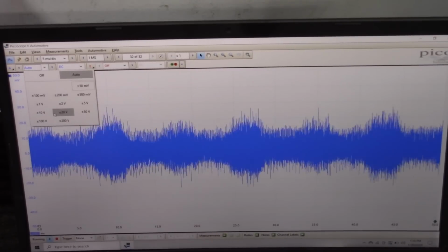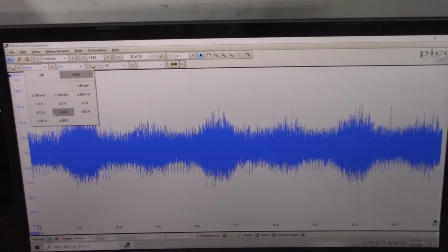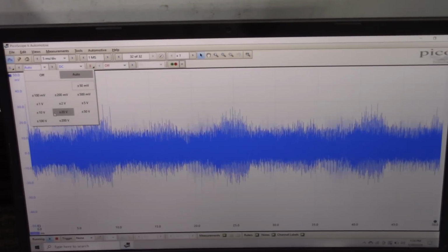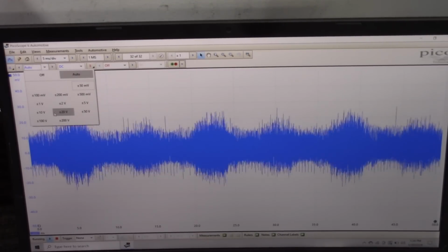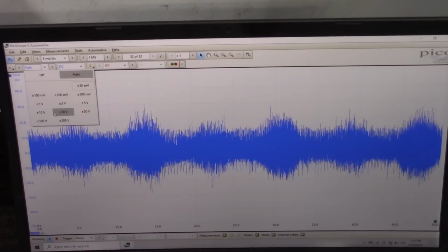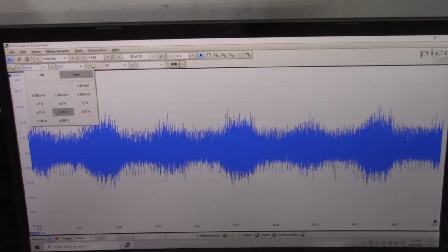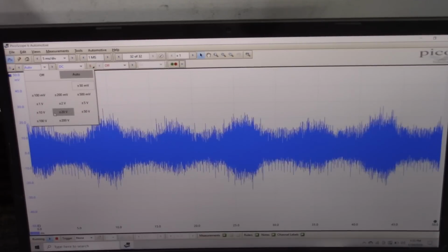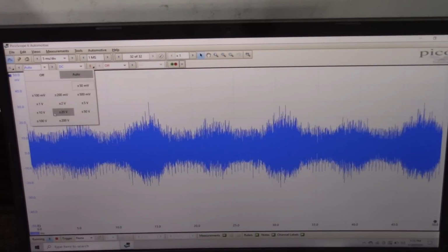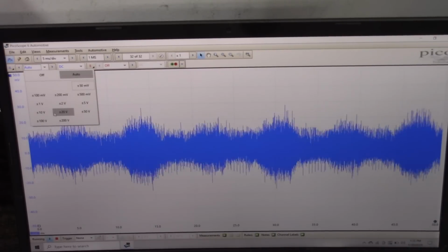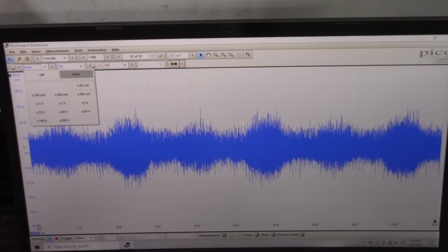Now, we also know, if you watch this channel, we're going to have a little surprise. We expect the voltage is going to be 12 volts, on or off, on or off, 12 volts. That's actually not going to be the case here because, again, this is a solenoid essentially. And we know when the solenoid turns off, it's going to actually generate a voltage from the collapse of a magnetic field in its own. So we're actually not going to see quite what we normally expect with just a simple on-off like I showed on the board. But we are going to still see ground side control here.